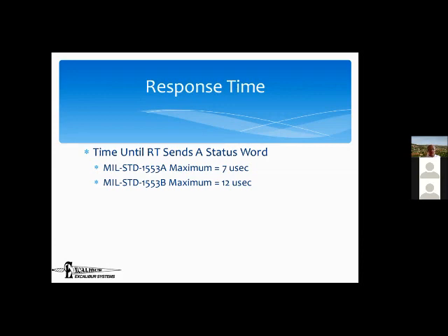Another thing that could affect the response time is, we'll see later, there's a thing called a bus repeater. And a bus repeater extends the length of a bus, but it does take extra time. And so even if the RT is fast enough and responding in 11.5 microseconds, by the time it goes through a bus repeater, it could go up to 12.5, 13 microseconds, and therefore the bus controller wants to wait a little more time. Now, in our cards, we allow the bus controller to set what we call the response time window before it gives up.